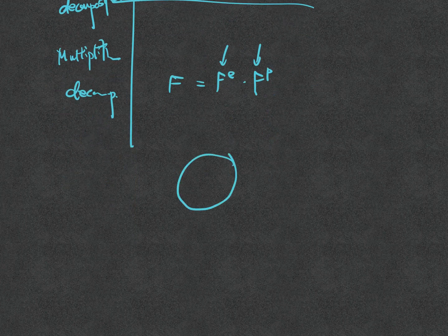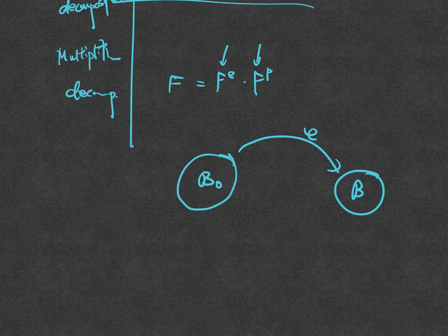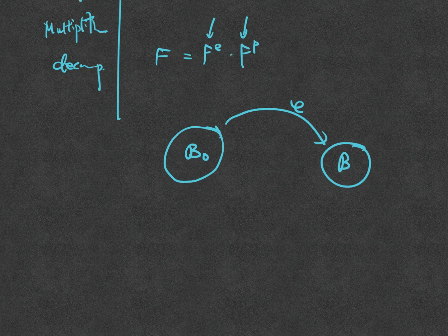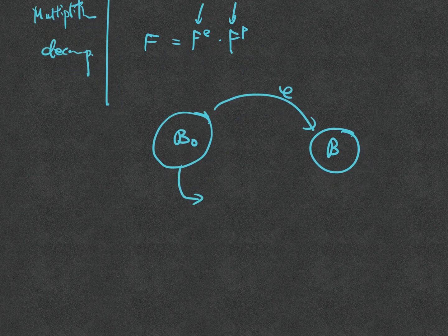I have a body that is undeformed. Now I apply the total deformation to make it deform, and I change the shape. What the multiplicative decomposition is doing is that I assume I can first deform it in some way, with the linear mapping Fp, so that it is deformed without changing the stress or energy.